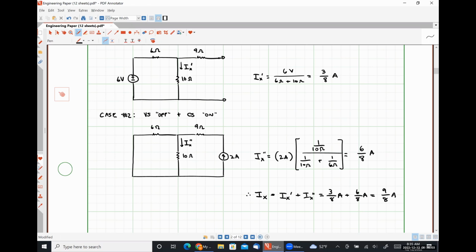Yes. Was the circuit analysis that we did using the superposition principle easier than when we treated the circuit with both sources on at the same time? In this case, I would argue yes. An Ohm's law relationship and a simple current division relationship, and then we added the results together, okay? This will not always be the case. It depends on the circuit that we're looking at.